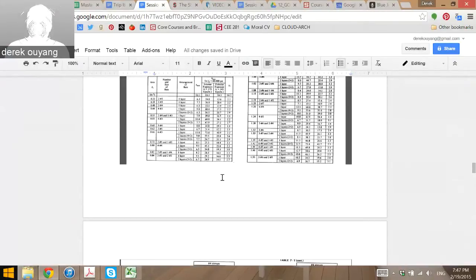So you guys are using that quite a bit, right? Have you guys tried to put this into this to get rid of A? Have you done that? So it's what that looks like. So then this is going to be equal to phi As Fy D minus, and then you put A in there, so it's As Fy over 0.85 F prime C B, all over 2. Okay. And then what can you replace As with? Where did you get As to begin with? Sometimes you do this in reverse if you're doing analysis versus design. But As is really related to the reinforcement ratio, right? And either you're setting a minimum or you're given one and you're checking if it's greater than the minimum or not. But what As really is, is rho times BD, right? You guys have seen this?